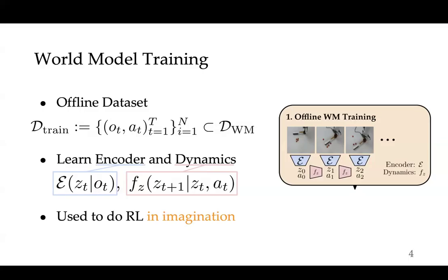So once we've built a strong enough world model with some data from the robot, we can start to use this now as a simulator, right? We can take an initial latent and then start trying out different actions that we've never seen before, and see how that might affect the robot. It's almost as if we're rolling out the robot in real life, but this is happening in what we call imagination. So it allows us to do these experimental rollouts for free using reinforcement learning.